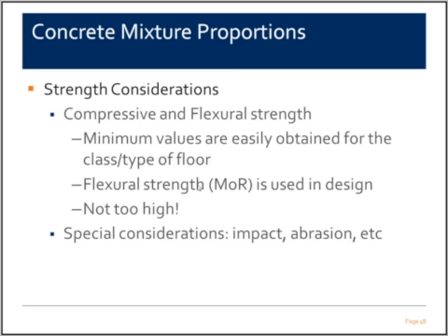We definitely don't want our compressive strength to be too high. If our compressive strength gets too high, this will also increase our modulus of elasticity, making our concrete more brittle, which can lead to additional random cracking. Some special considerations where strength is more important include impact resistance and abrasion resistance. So these have to be considered in more detail when we have slabs with those concerns.